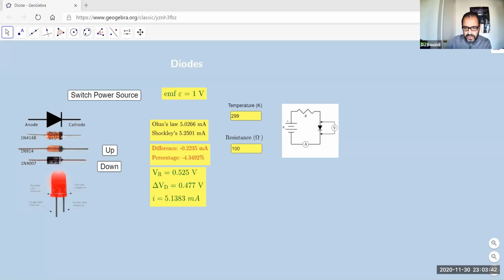How much was the second resistor? It's 270. So we're going to change 270. It's probably easier, because that's what we really should do in the lab. So now the error is in 270. If the error is negative, and I need to bring it up, I'm going to go down in here. It's counterintuitive, but hopefully you understand. We're going to go up and down until you find an error within less than 7%.